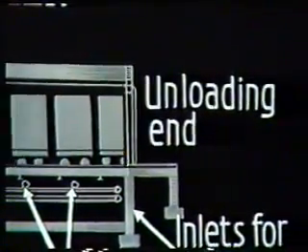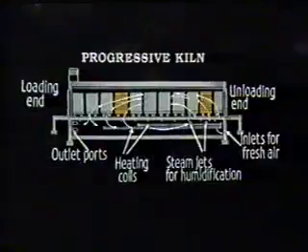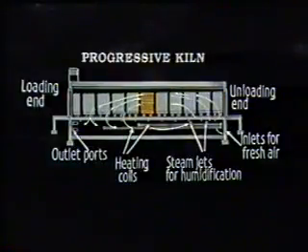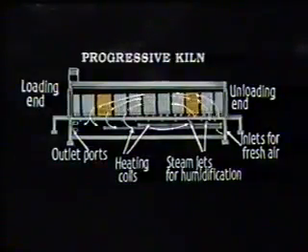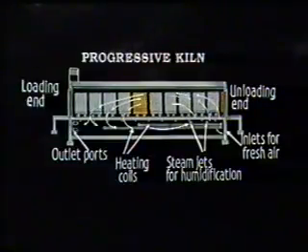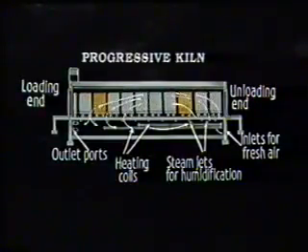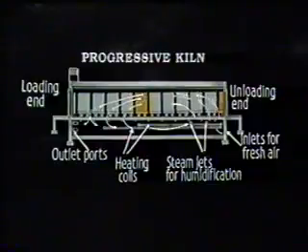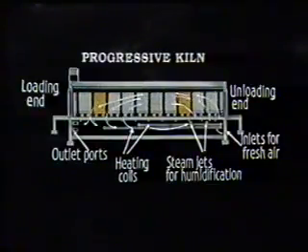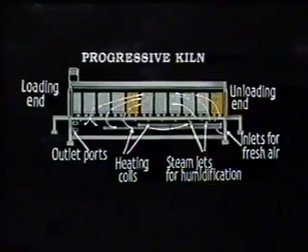Steam is normally used to heat the air and water sprays for controlling humidity. The airflow is from outlet end to inlet end. The progressive kiln is suitable for large quantities of timber of the same species.